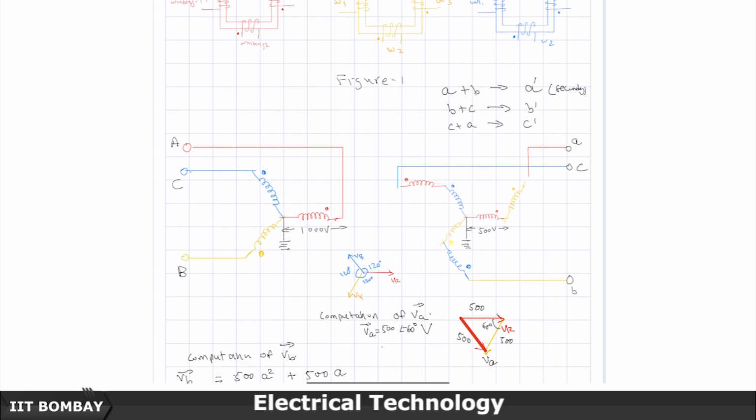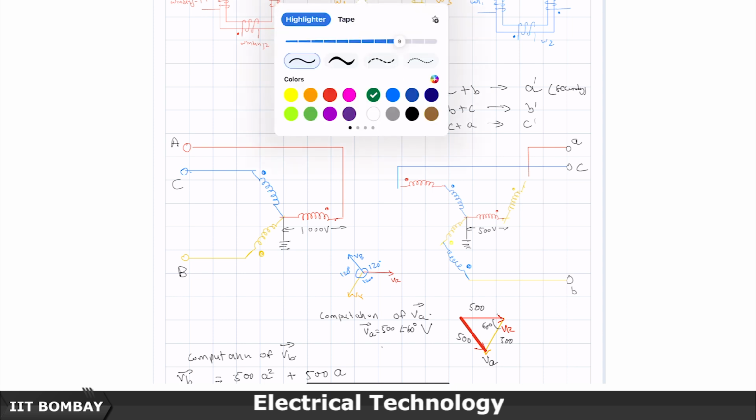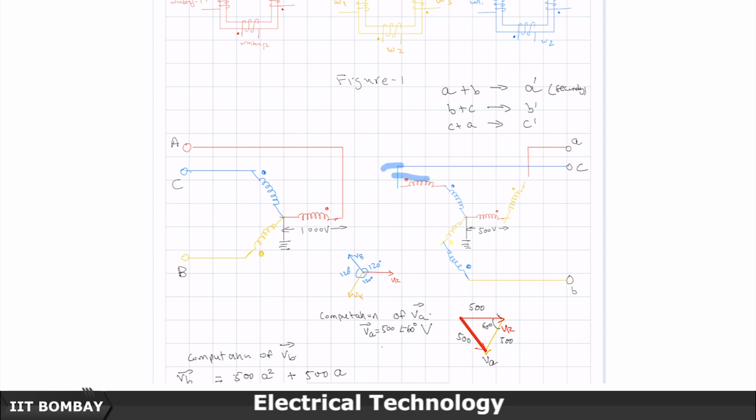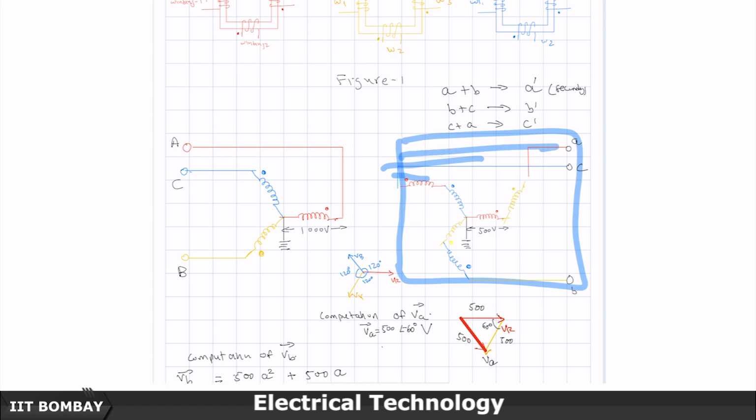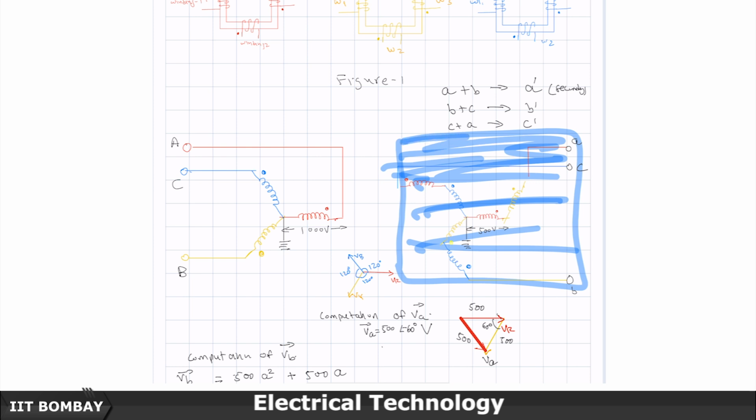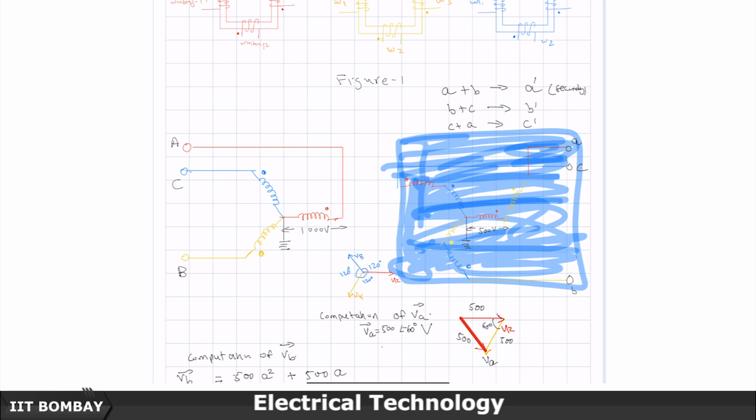Suppose this part was simply not there. Imagine that this is all not there. I will have to rub it later on, that is going to be a bit of a problem, but it is okay. Suppose this part was not there, and I have this one side which is ungrounded. So, there are safety issues, and issues like I cannot carry the current if there is a ground fault, you will see that later, and the currents have to flow to the ground. So, if some conductor has broken and fallen down, then I am not able to provide a closed circuit path. A conductor has broken and fallen to the ground, but my source is ungrounded.